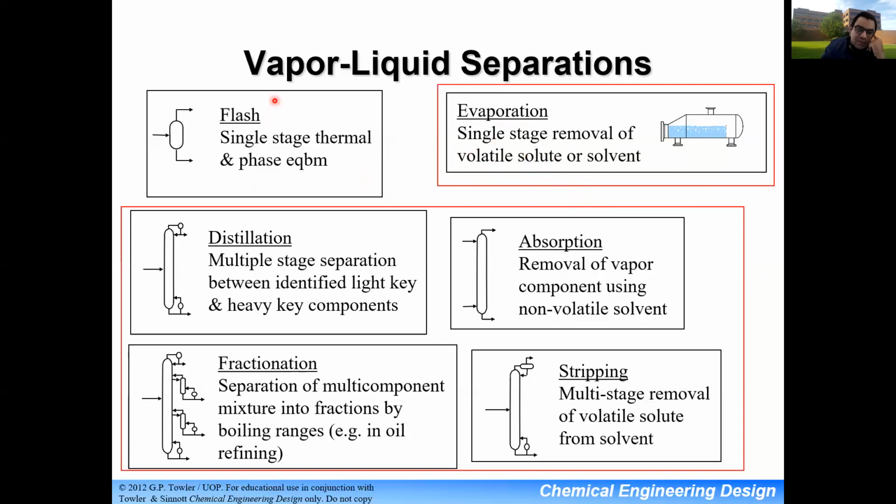Whereas a flash tank is similar to opening a Coke can or a soda can, because the soda can is pressurized, once I open it, I suddenly reduce the pressure, so the gas or the CO2 bubbles out, right? So I'm just inducing a change in PT conditions to change the thermodynamic state of this mixture. Distillation, I just talked about distillation.